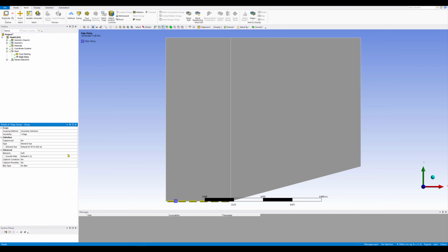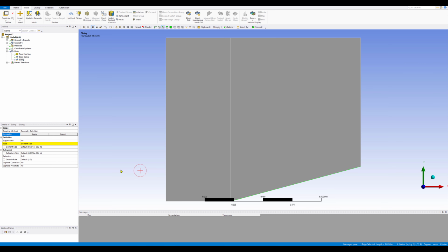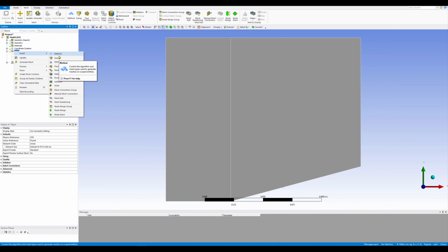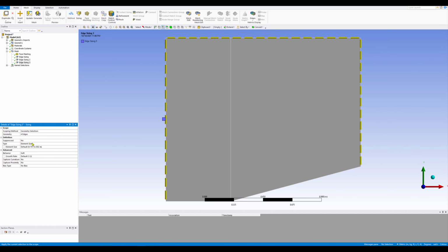For example, you can select here, and then in the element size you can put 0.01. I will add another sizing for this wedge, the same. Because these are the same, you can select in one sizing, but here I'm adding three for each of these boundaries. So I need one more for the sizing. I will select these 4 edges, Farfield edges, and then press apply, press 0.01.